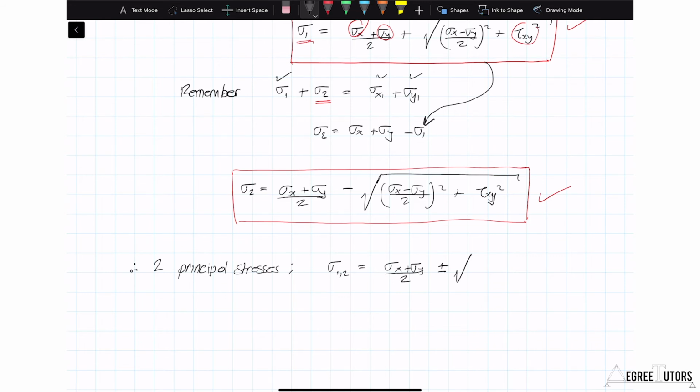And if we draw that out or write that out longhand, it's the following. All right, this is pretty fundamental. This is pretty important to us, because what this is telling us is the maximum and minimum values of normal stress. I keep emphasizing this because it's really important to us. So let's just go ahead and calculate some numerical values for these and plot them onto our plot. So now, and let me just put a box around this, right? This is what I'm about to plot onto my graph here, right?